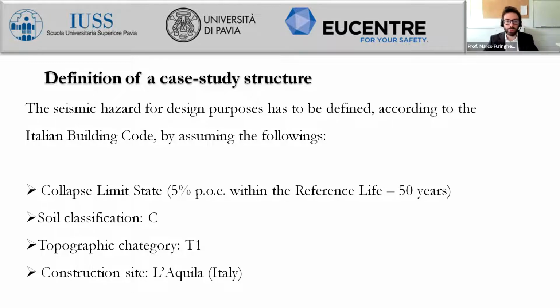So according to the beginning of our definition of the case study structure, the seismic input will be considered as the target spectrum provided by the Italian building code according to the following assumptions. So the collapse limit state, which is related to 5% of probability of exceedance within the reference life, which is assumed for 50 years for ordinary buildings, let's say.